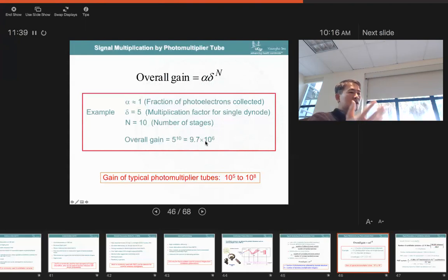Again, the reason we want to amplify the signal is that we are really talking about a very weak signal. We calculated the charge from a single quantum of interaction before, and it's a pretty low value. So without amplifying, basically making more charges and a bigger current, you can't get a measurable voltage out of any electronics.